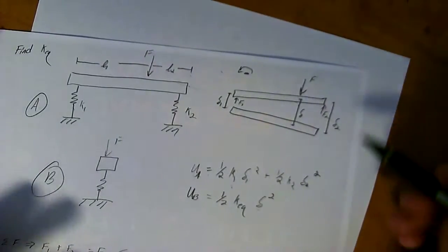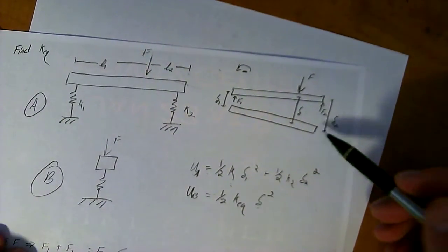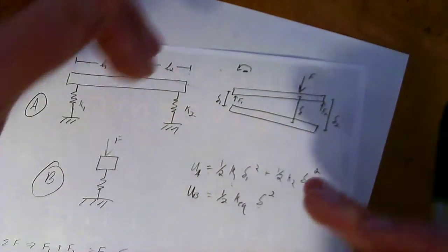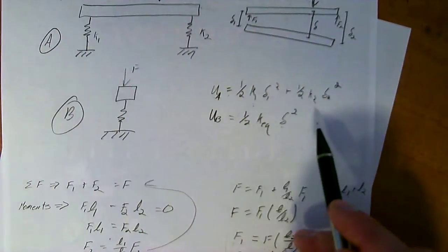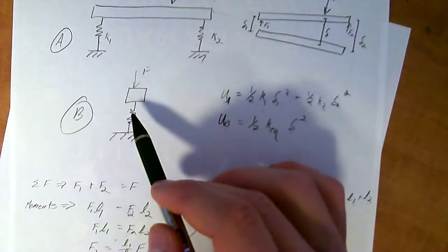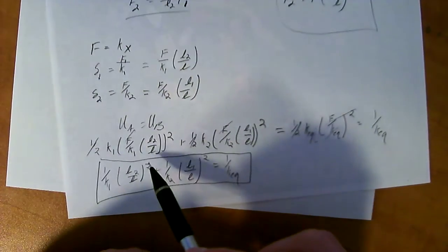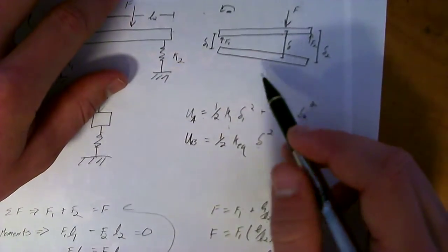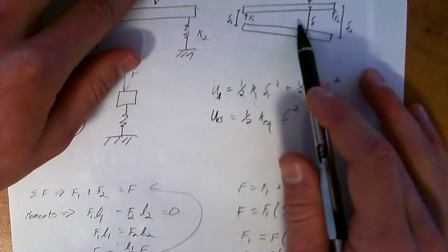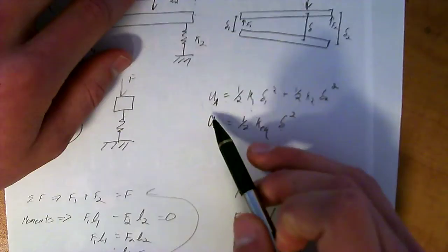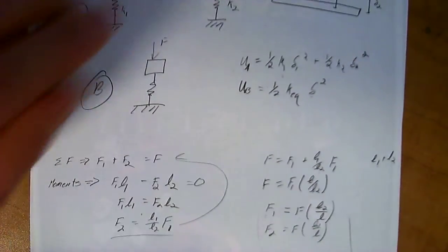You basically have to find the relationships in the deltas, the displacements, with respect to the force being applied and the bar being moved. Find the equivalent energies for the full system and the equivalent system, and then move on down, calculate, and you get the final answer. So it's really not too bad. You just have to remember how to do the forces with respect to a specific location so that it's still accurate, and then also remember how to set up the energy equation. Alrighty.